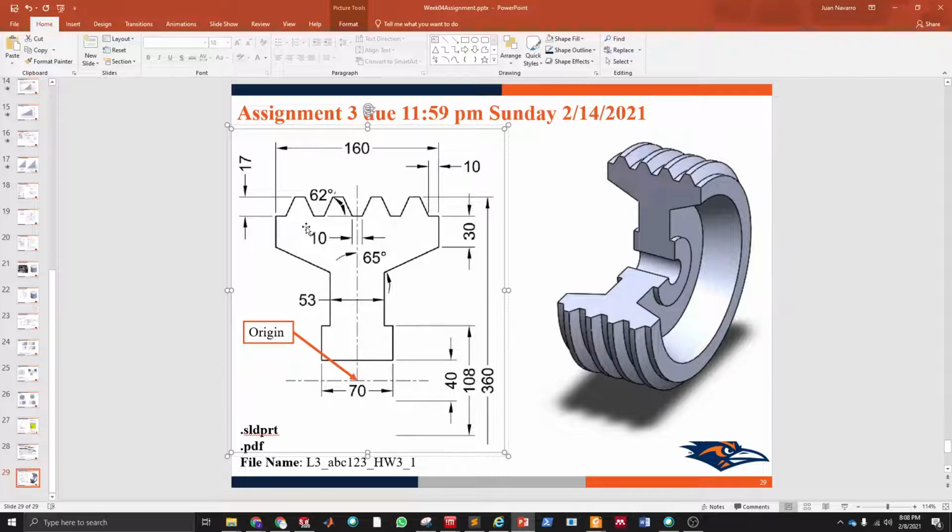You can assume that the lines in the bottom are also the same length. All of them are these 10 millimeters. But an important thing here is that you don't know the length of the lines in the top. You will actually get them by construction. And that means you will not have to define them. And still, this will be fully defined.